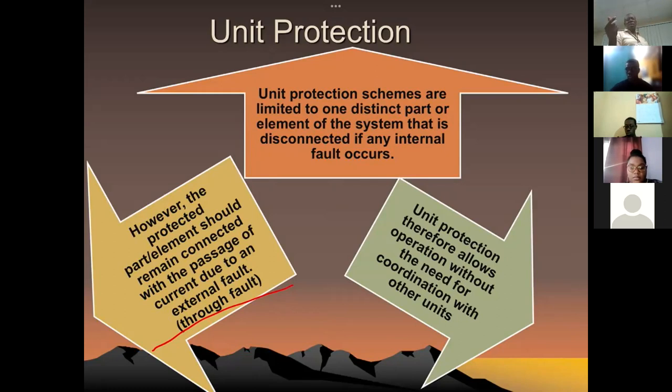If it exceeds a certain value, then it may cause a breakdown of the insulation that you're using, again depending on the wavefront that you're dealing with. You have insulation damage and you end up damaging the transformer. High currents through the transformer can also result in physical damage to the unit. And we'll talk about that when we delve a little more into transformer protection.